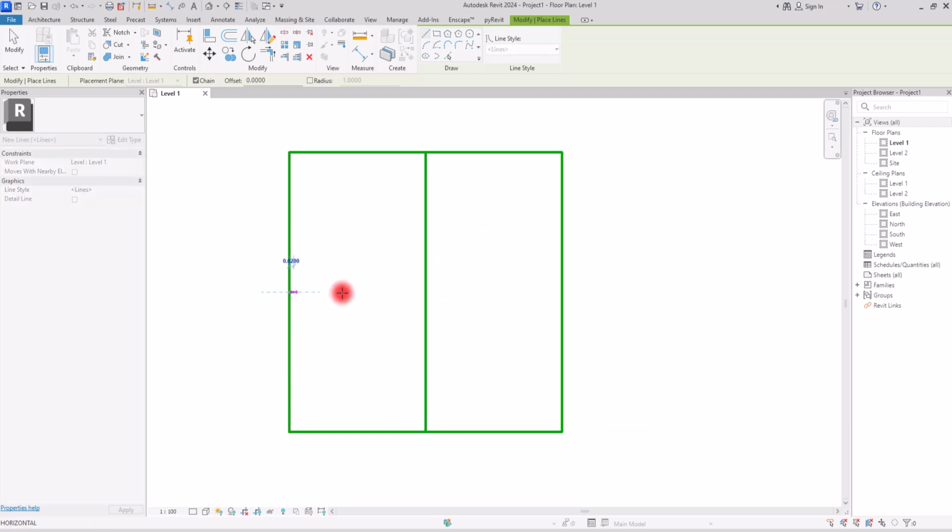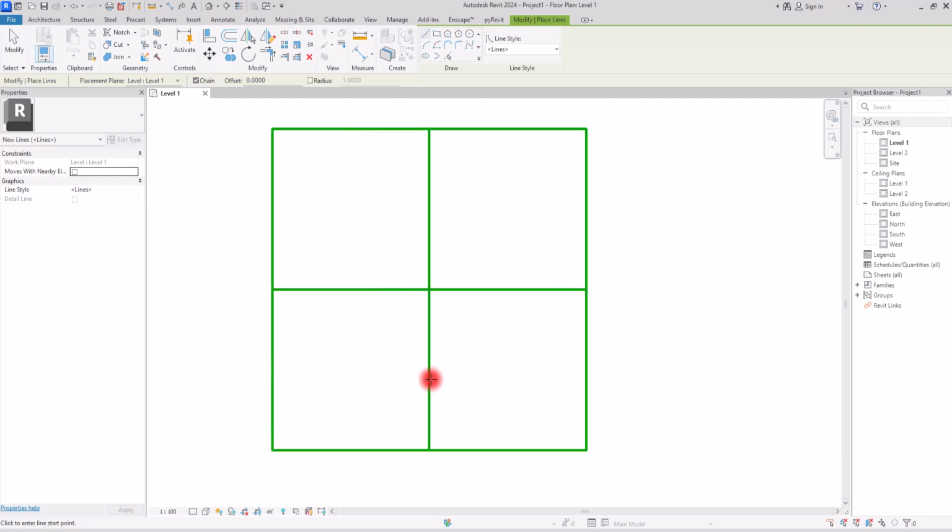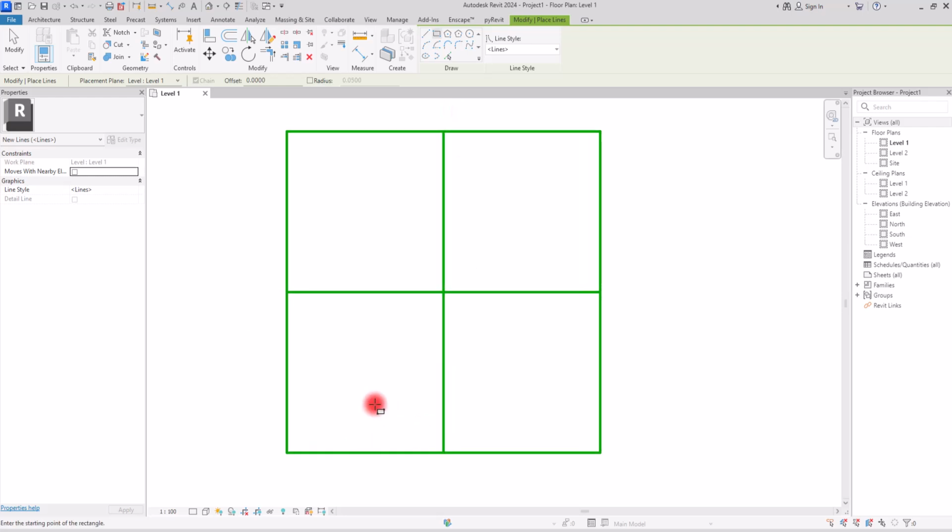This pattern is a little different and it might be a little challenging because we are going to use these parts as empty sections. Okay, I'm going to use this rectangle inside this part with 21 centimeter offset, from this corner to here. Press space if you want it to be inside. Then I'm going to use this pick line with 7 centimeter offset. I'm going to create lines on both sides of this rectangle. Okay, and in this part.